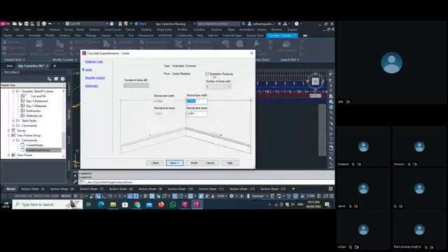See, in a symmetric roadway, what happens? If you have a right side and a left side, these two sides are the same. As we have 3 meters of length, the total lane width is 6 meters. As you have the same lane width here, you can select the symmetric view. If you have a different slope or a different view here, you can uncheck it. But I have the same view, so I can set it as symmetric. Then whatever the lane slope, I have the 2% slope, it is okay now.